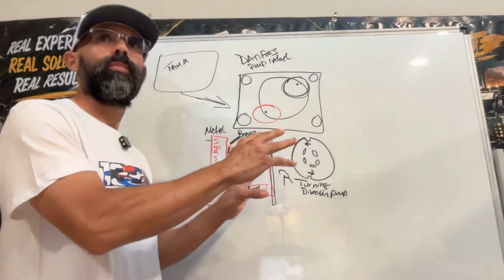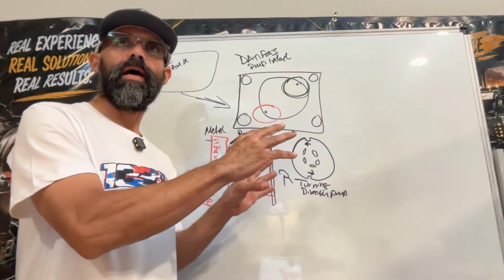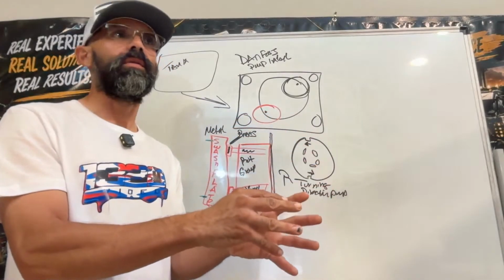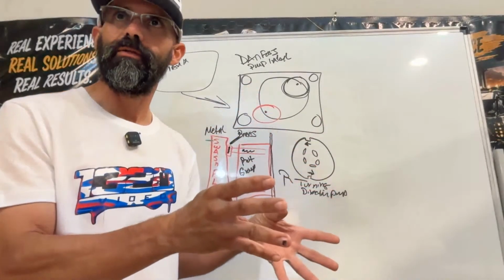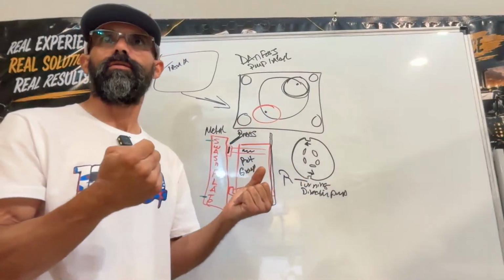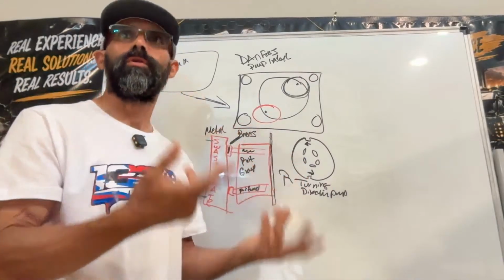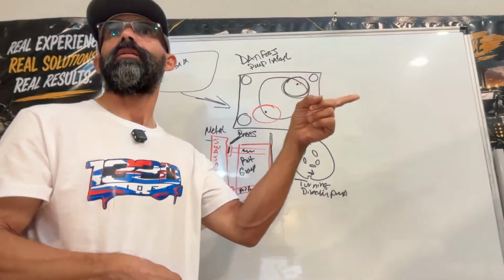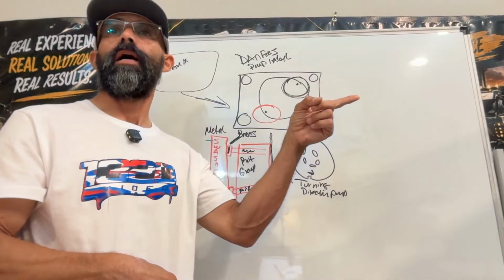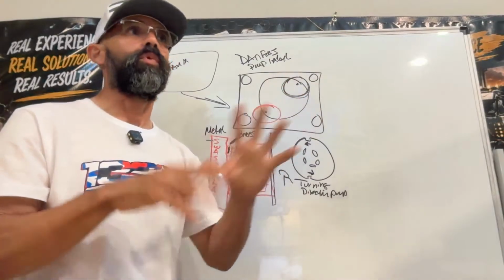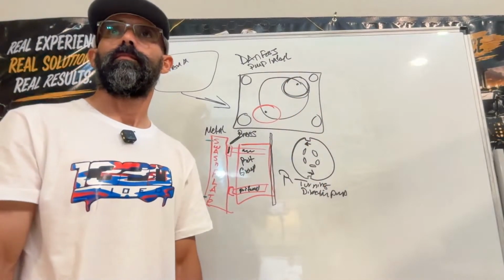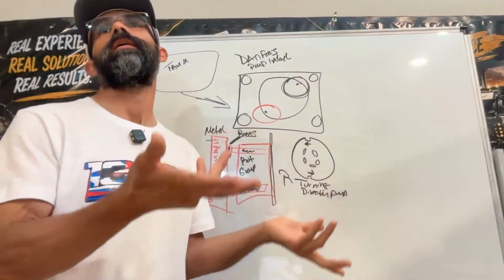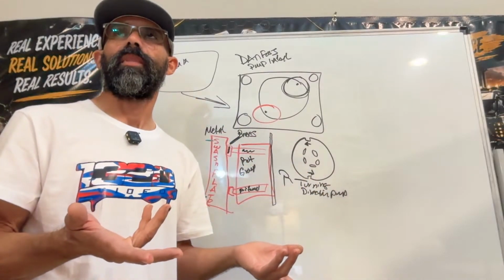So do the process, do it nice, neatly, clean, inspect everything. If you've got to use, like I said, a magnifying glass, use it so you can see. There's nothing wrong with that. Use them, so that way you can identify, hey, wait a minute, something traveled through the hydro system, ended up on the pump, boom, destroyed the pump. Or water intrusion, foreign material, dirt, whatever, you can identify it.